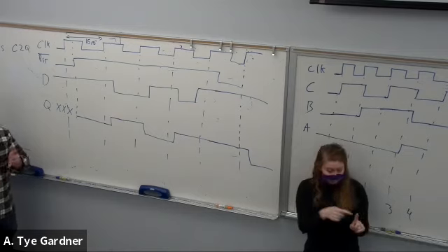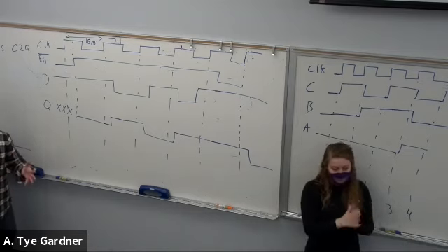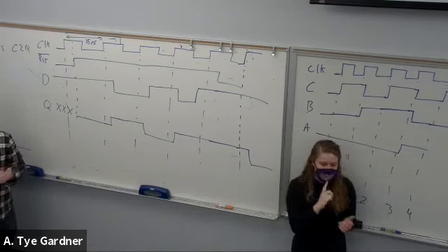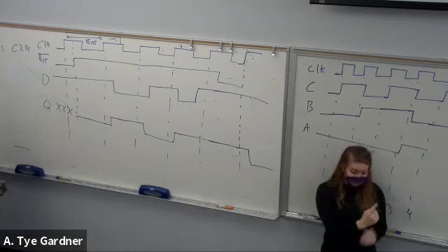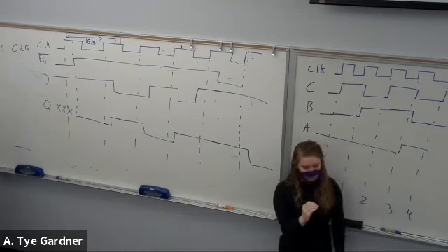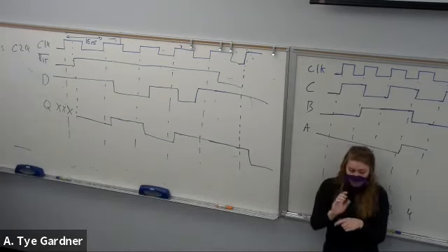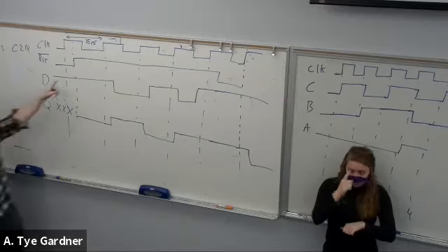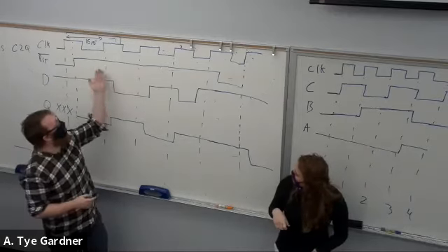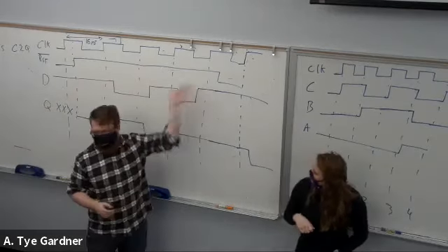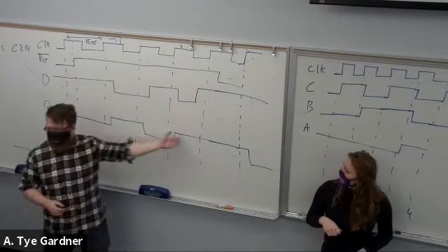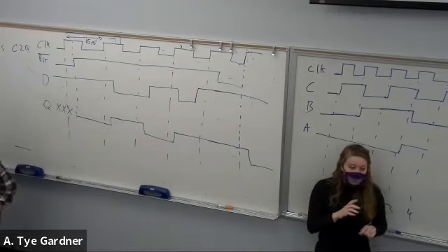And that's just vocabulary, really. It's just definition. It's set, 1, reset, 0. Okay. And the reason you did the invert reset, right, is so that if that wasn't there, it would reset if it was high. Yes, exactly. So then we'd be resetting this entire duration except for the very end. So we'd be just zeros most of the way, and it would have been way less interesting.